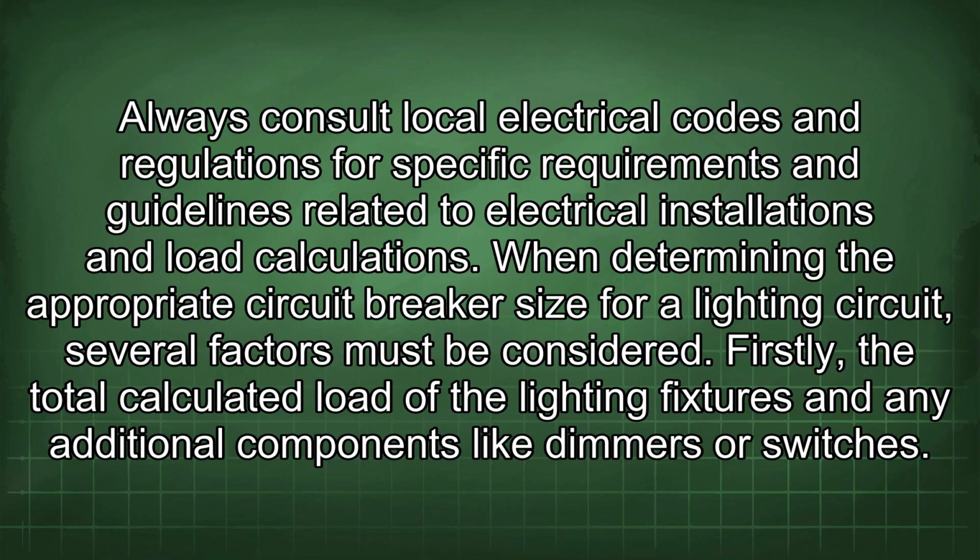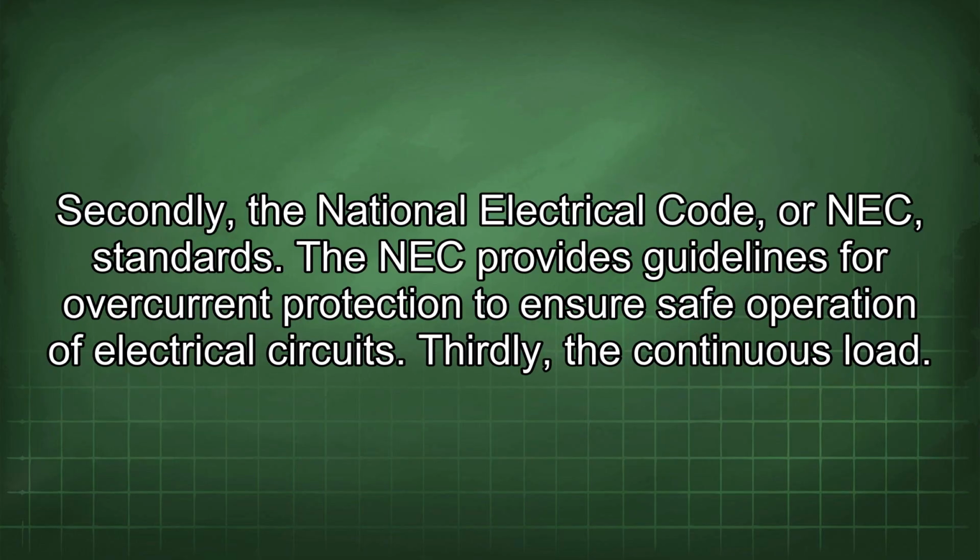load calculations. When determining the appropriate circuit breaker size for a lighting circuit, several factors must be considered. Firstly, the total calculated load of the lighting fixtures and any additional components like dimmers or switches. Secondly, the National Electrical Code, or NEC standards. The NEC provides guidelines for overcurrent protection to ensure safe operation of electrical circuits.